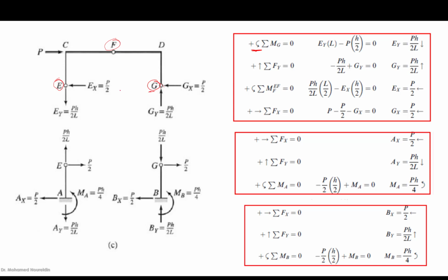Based on this, we have only one component, which is the internal force in the member CA, which we're going to call EY, the vertical reaction here, times this distance, which is the bay distance, L. So EY times L.